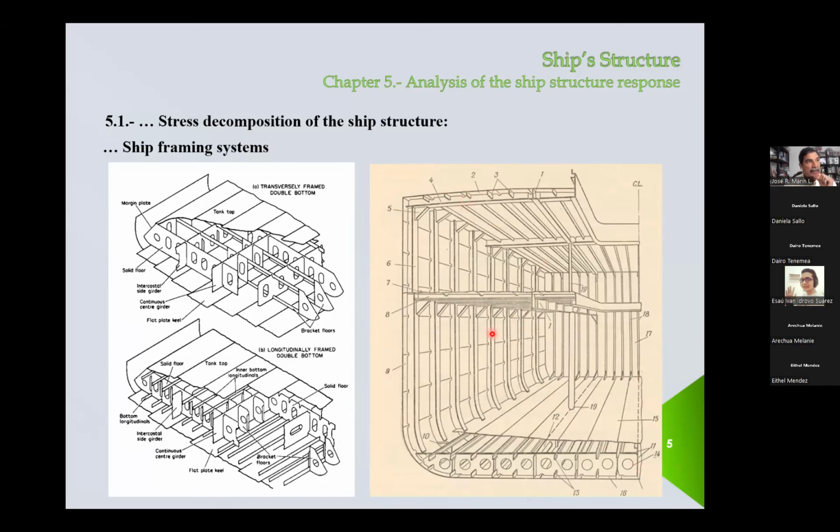For example, here, you need to weld the two plates. And that welding has to be continuous in order to avoid leakage. It's very difficult to be sure that the welding is continuous. So in this case, you have to include some lightening holes.